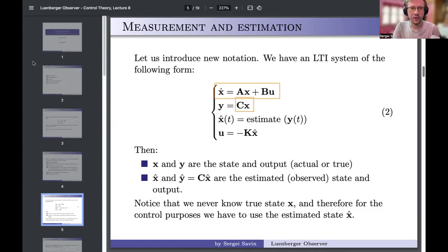And now with all of this, we can have a different part which can happen inside the microcontroller, right? What I showed in orange here is stuff that is not available to our microcontroller, because it's just stuff in the world which we don't have any way to get. But what I showed in blue is directly available to the microcontroller, because y is being directly measured, transformed into a number, and sent through the protocol directly to the port of our Arduino or Raspberry Pi. And this stuff in blue is computed inside the controller.